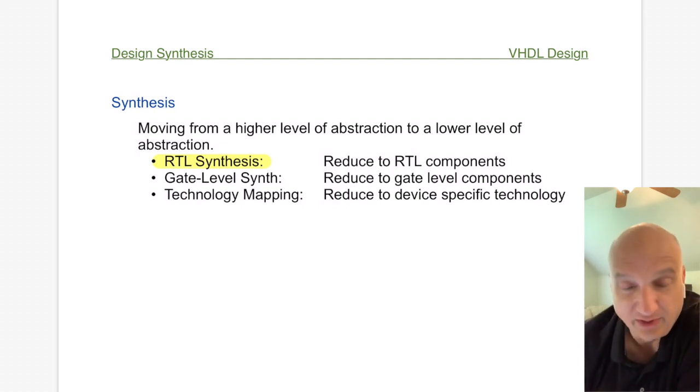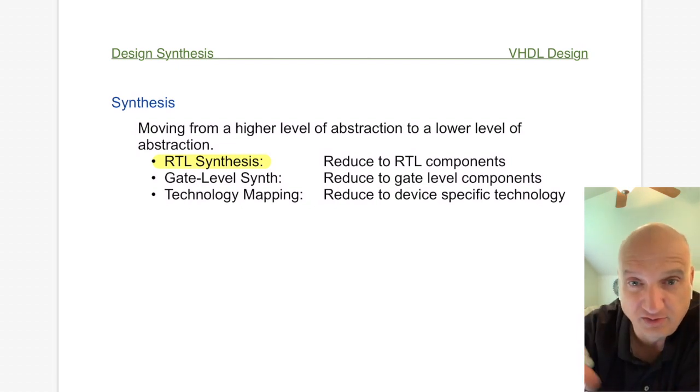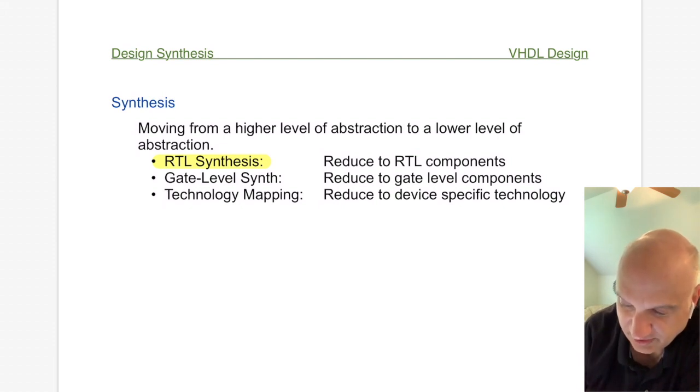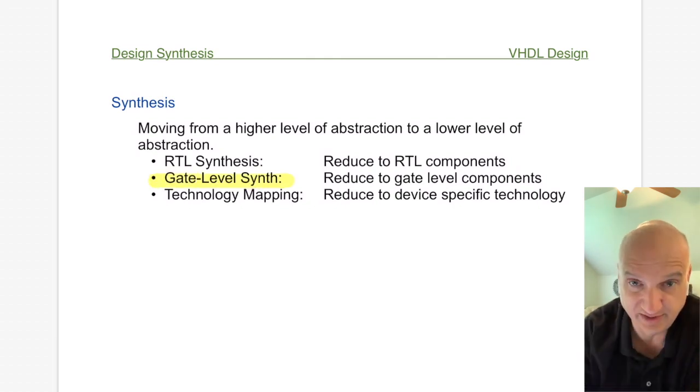And when we do an RTL synthesis, we are reducing all of our design, or our high level description, down into individual register blocks. Gate level synthesis is basically reducing your design down to just gates.